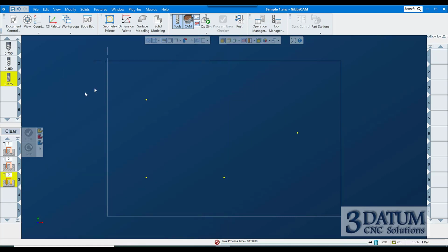So what I've done is I built everything that's going to these same hole locations. Now if I had other size holes, these wouldn't be in here, and I wouldn't add the stuff for the other holes down here. This is only for the toolpath that I'm creating right now. The toolpath I'm creating right now is these holes. So anything that's part of these holes can be in this list. Anything that's defined by these 4 point locations can be in this list at the same time. All right, so I'm going to select all of those and say do it.